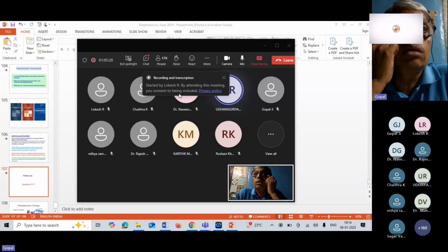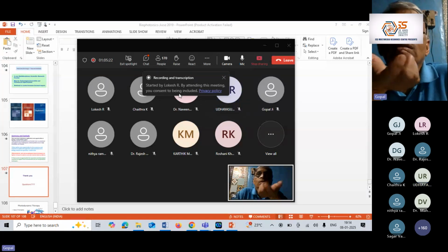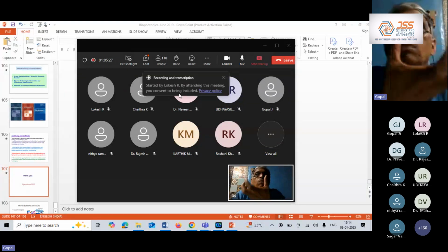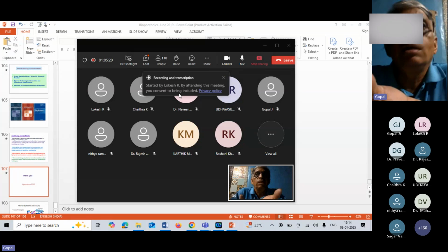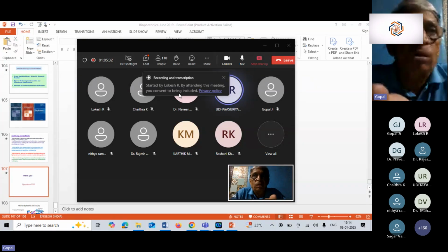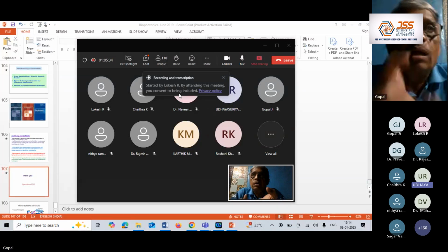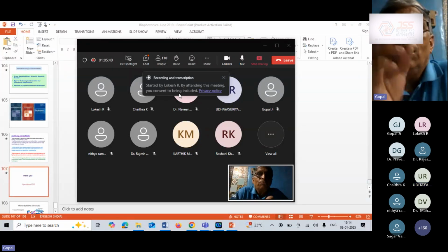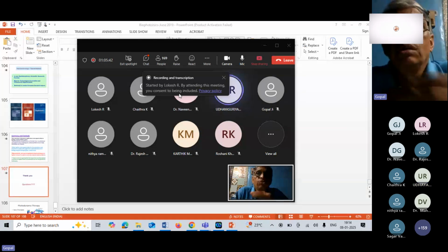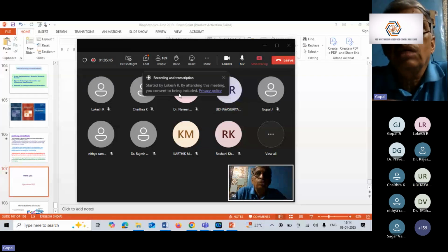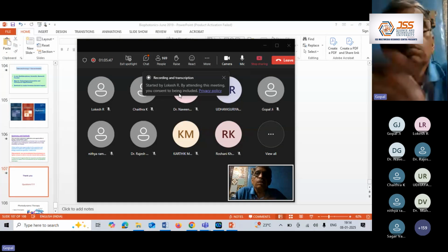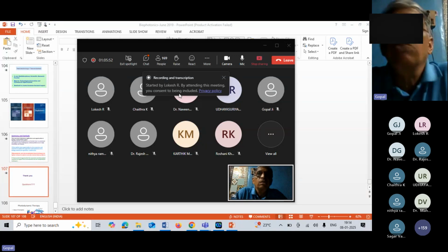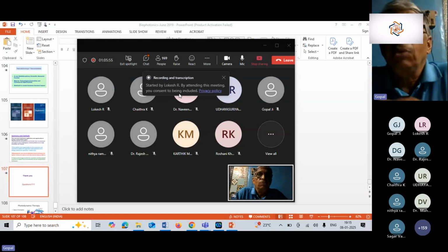No. See, for all these things there is always a limitation. The minimum level of nanostructure you can make is around 5 nanometers. I cannot say it is 100% reproducible; maybe reproducibility is 50% or 30%, and large-area uniformity may also be difficult. So that's a limit.